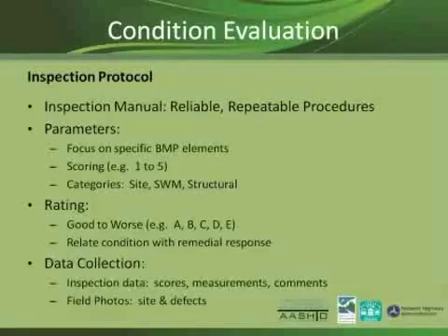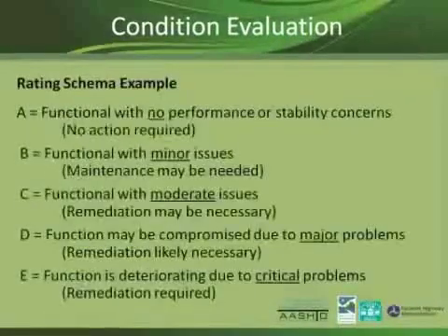What's good about the rating is you can relate it to not only the condition, but potential remedial actions. And all the while, inspection is always collecting data: scores, measurements, for example, of ponding that's additional in the pond that shouldn't be there, and comments both on site condition as well as comments that can be utilized for remedial work orders. Same thing with field photos. You want to take pictures of the site so you see it over time, but also define specific defects. Next.